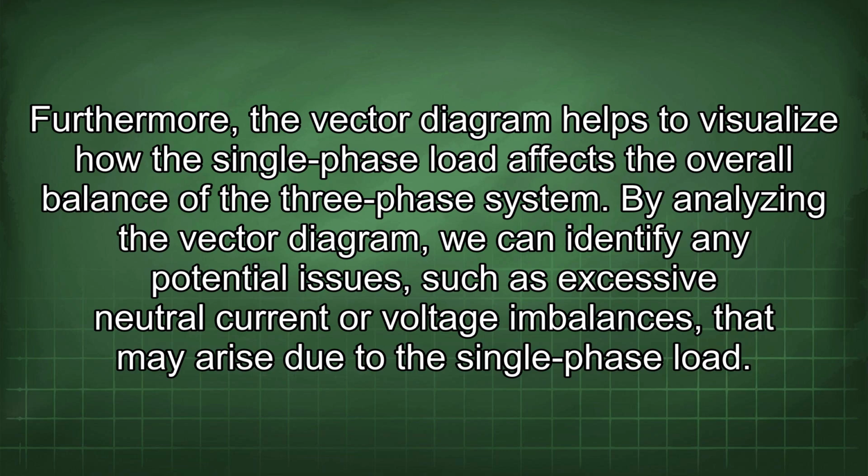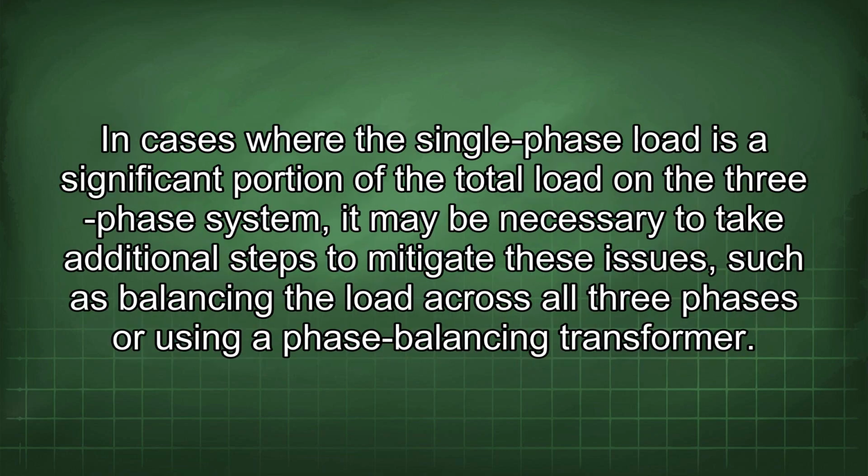By analyzing the vector diagram, we can identify any potential issues, such as excessive neutral current or voltage imbalances, that may arise due to the single-phase load. In cases where the single-phase load is a significant portion of the total load in the three-phase system, it may be necessary to take additional steps to mitigate these issues, such as balancing the load across all three phases or using a phase balancing transformer.